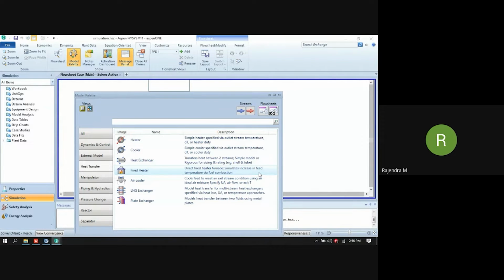Inside are the tubes, which may be finned. Of course, usually the tubes are finned. Because air is an external fluid which is freely available, the heat transfer takes place based on the ambient temperature as well as the process stream temperature, and we can model the air cooler by using this palette.